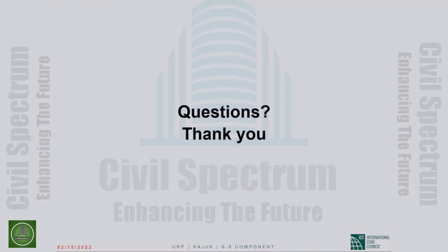So it is not that you need to check drift to figure out whether to do static analysis or modal response spectrum. It is the other way around. You make a decision based on whatever your design shall be based on, modal response spectrum analysis, probably because you have a tall structure and an irregular structure. And then you will have to do drift check as always, and you will also have to account for torsional irregularities if there are any. I think he got answered.